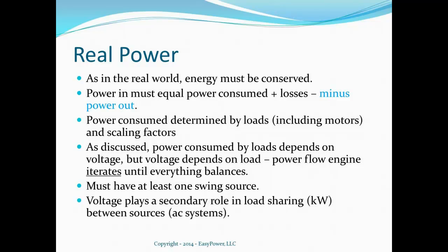And almost all loads are somewhat voltage dependent, some more than others. But the voltage that the load sees depends on the load, because you have voltage drops in the system, like across your transformers and in your cables. So those two things are interdependent. The only way to solve that is to iterate until everything balances within the accuracy that you specify. Basically, the program's going to iterate until everything balances out.